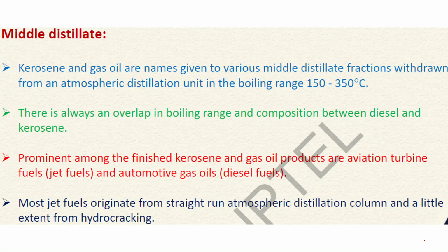Now coming on to the middle distillates, they are basically the distillate content which comes after gasoline. Firstly, it is LPG, which is given as overhead. Then it is naphtha. Then after that, it is gasoline, and then there come kerosene and diesel. This kerosene and diesel cut is collectively called the middle distillate.